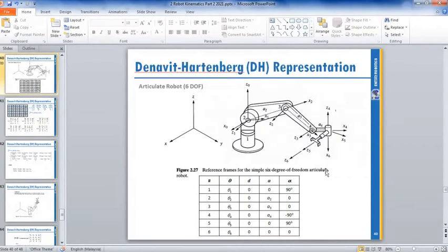They differ in your homogeneous matrix because of your link length and also your joint connection. Maybe at one joint you change your direction from horizontal to vertical. Then you have a different DH parameter table.